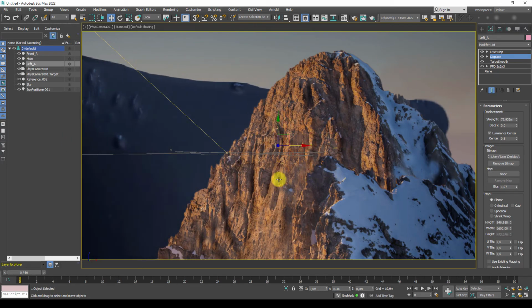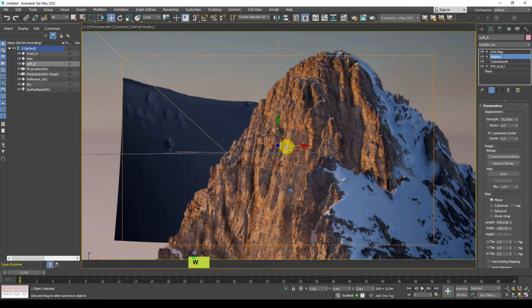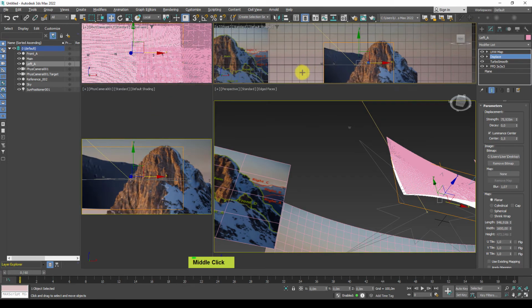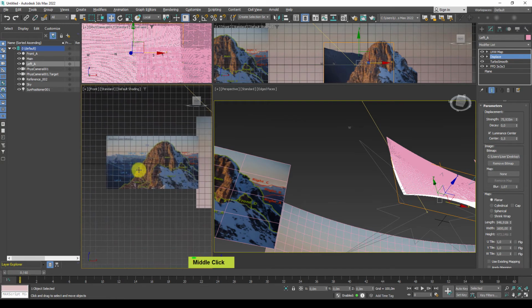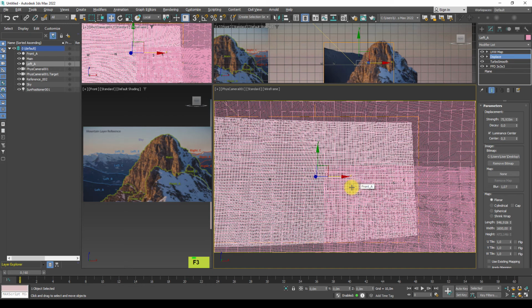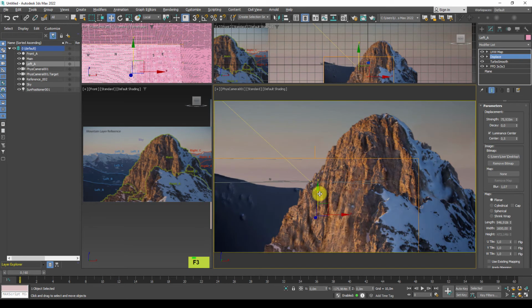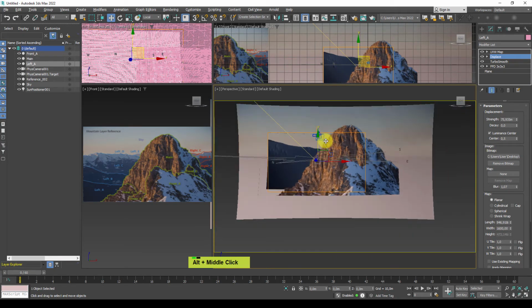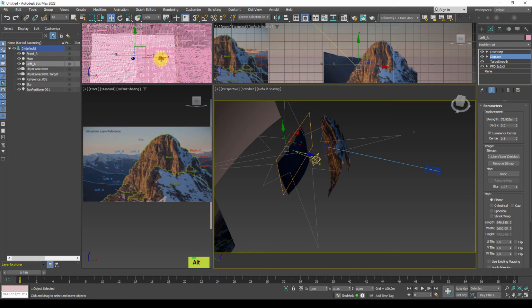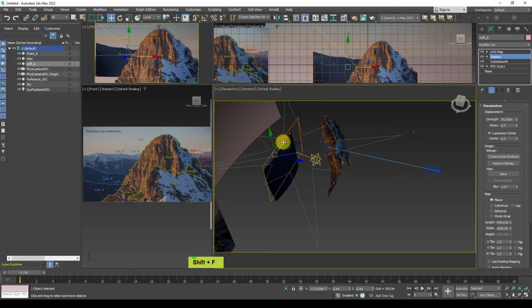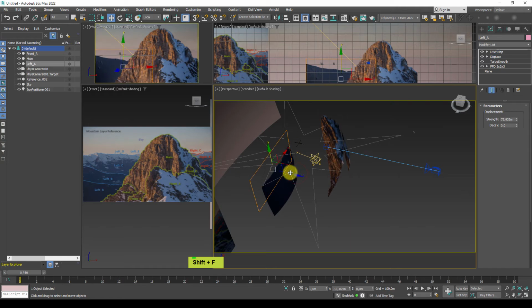So we want to go in and use the scale, and we will use the reference as well. So where it should be, Alt W, and I'm looking for this. This will be a simple front, Shift F, and on this view, G is to hide away geometry. I'm looking for the proportions. So camera, function key 4, and see where it goes. It's really smaller, and one way to solve it is to put it behind, and that will be camera, Shift F.